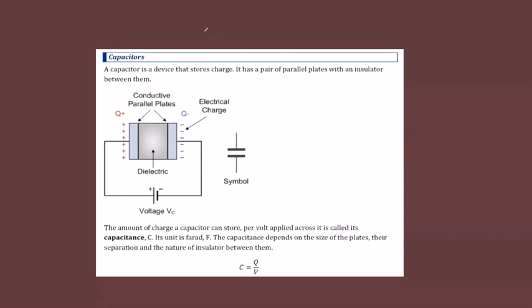And if we connect a high voltage supply, the capacitor stores a greater amount of charge. So if we sketch a graph of voltage and charge, with charge on the y-axis and voltage on the x-axis, there will be a straight line, which shows that increasing the voltage across the capacitor will increase the charge on the plate. And when we find the slope or gradient of this, what do we get? We get the capacitance. What is the unit of capacitance? Capacitance is charge per volt.